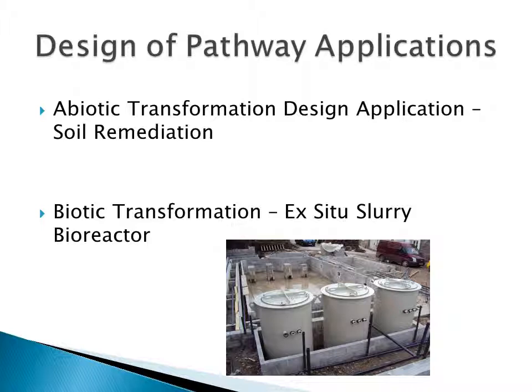In considering the process dynamics, the primary limitations in slurry phase treatment are desorption and biodegradation kinetics. Contaminant sorption is a primary consideration in the process design of bioslurry reactors. Because most biodegradable material occurs in the aqueous phase, the desorption rate often controls the bioavailability of the contaminants.